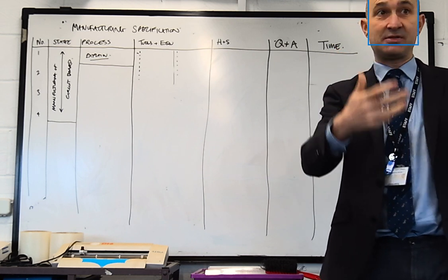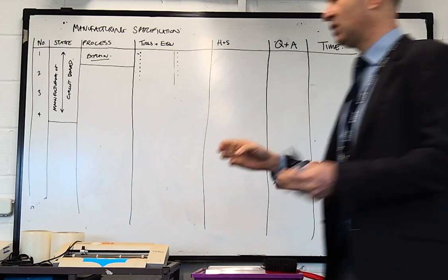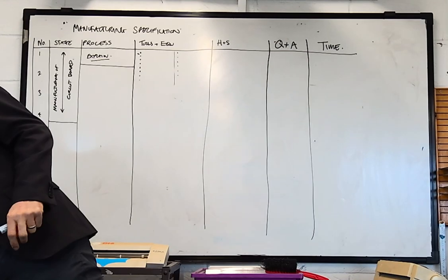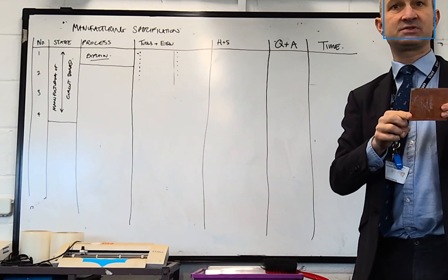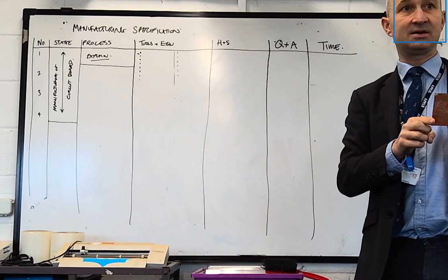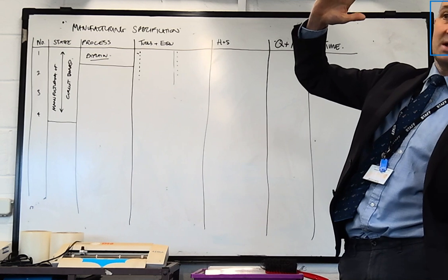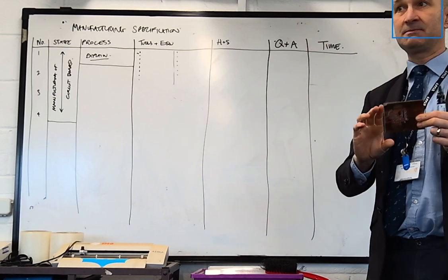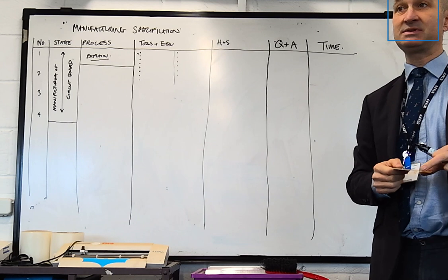That could be another thing that we're talking about in regards to cutting your piece of PCB. What do we want to make sure that each edge is? Straight, right angular, because we've got to put it into the holder, haven't we? And if we get some sort of rhombus, it's much harder to hold. We can do that quite easily by just putting the PCB up to the guide.